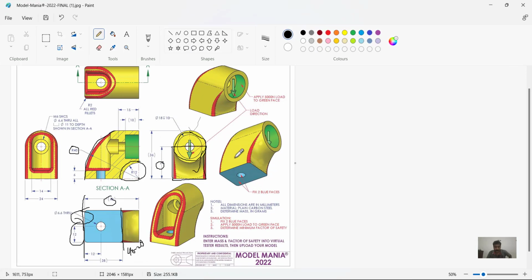So we achieve this shape at this point. Next thing is that we have to cut this shape. We are going to draw a shape like that and we are going to cut it. So from the bottom to this point, it has the dimension of 6, and we are going to select this bottom face and open this sketch and draw this shape. For the dimension of this shape, you can look here.